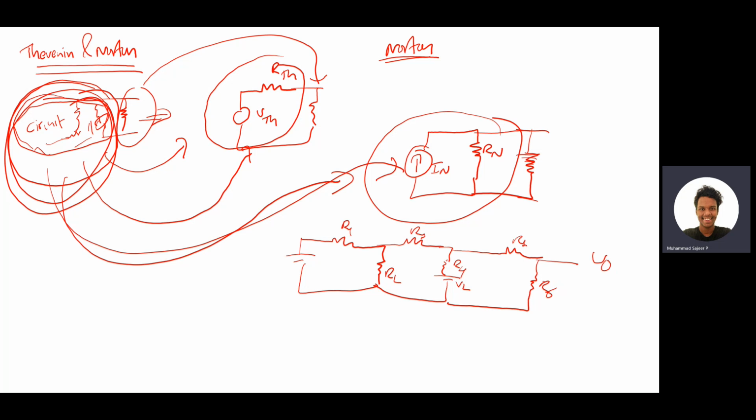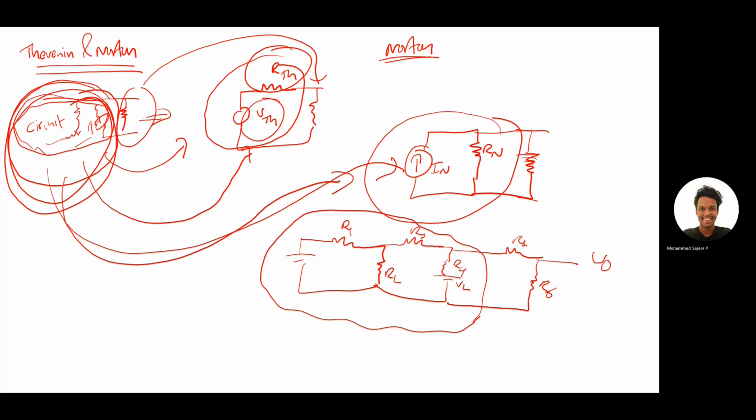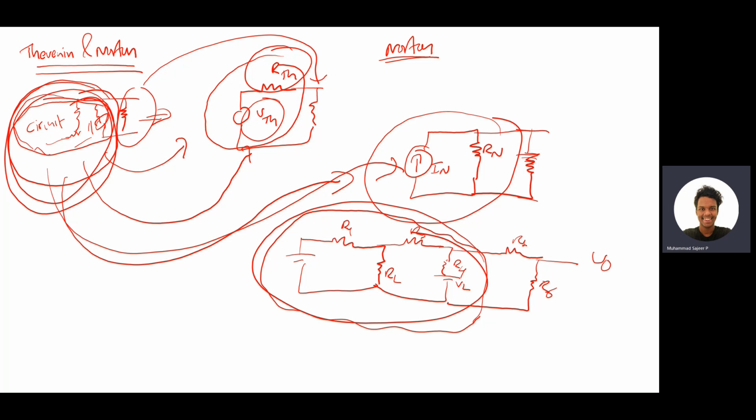Okay. So in the Thevenin, they will simplify. For example, if you want to simplify this area, as I said, we need a Thevenin voltage and a Thevenin resistance. So for that we will rewrite this big circuit, first for finding the resistance, the R Thevenin.